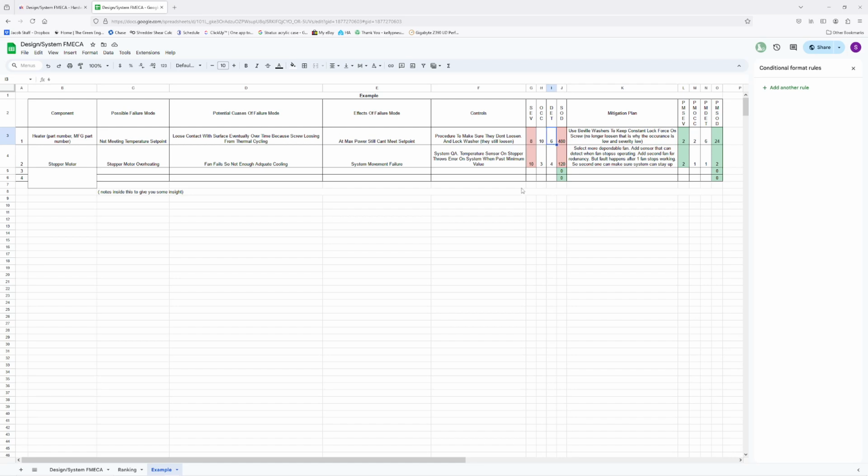Detectability: it's kind of hard to tell why the heater stopped functioning. Is it because the heater is defective? Is it because my wiring came loose? Is it because my heater driver has a problem? Is it because my software is not sending the right set point? Is it some sort of loose connection somewhere?